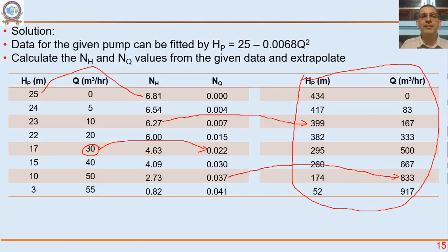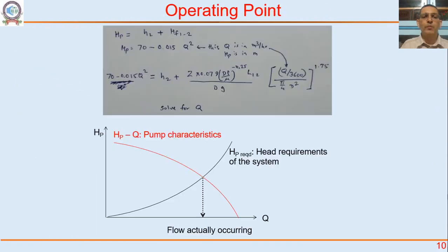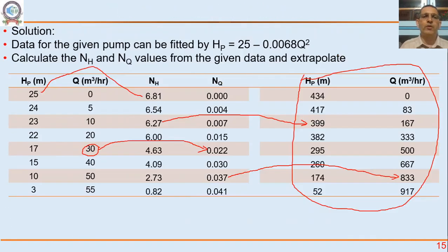We could not have the heart as a centrifugal pump, because the moment head increases, the flow rate drops dramatically. And if flow rate drops dramatically, we would have felt it by tingling sensation, giddiness, all those things. So you see, our hearts are nice positive displacement pumps, and therefore we don't realize that any problem is created even when the arteries are narrowed down.